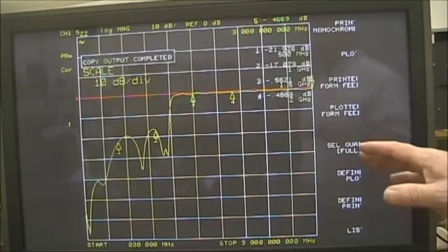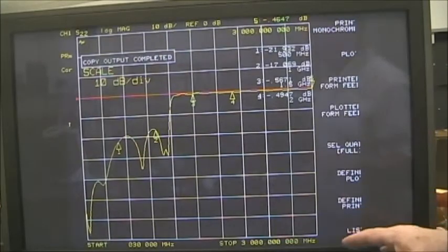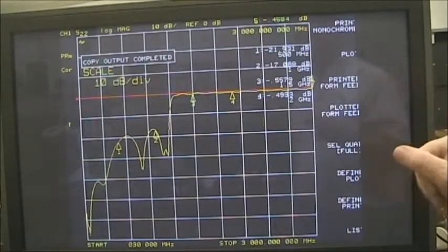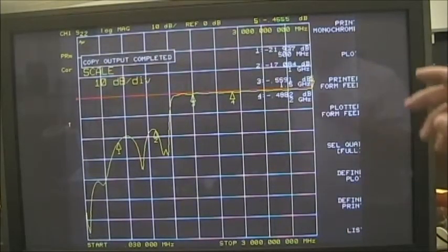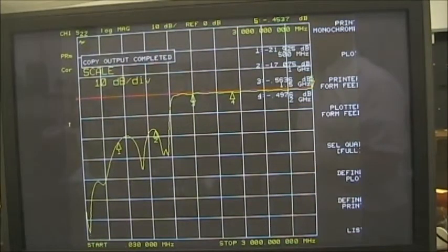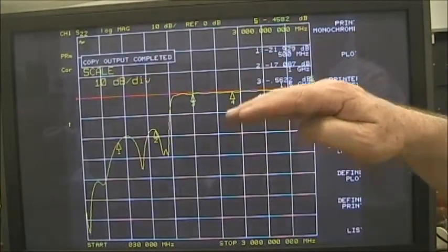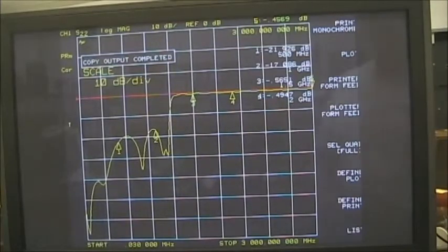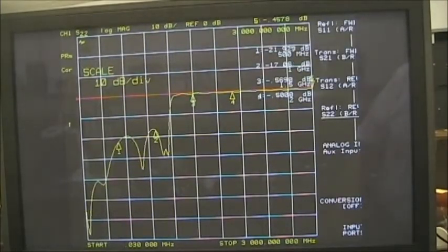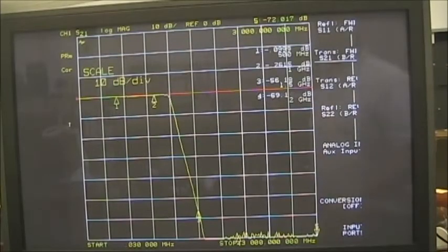So I have changed the element under test to a filter. Okay, so now on a filter, we know what filters should look like, right? This happens to be a low pass filter. We should expect to see a passing frequency and then a loss, right? So I'm going to select my forward path, right?